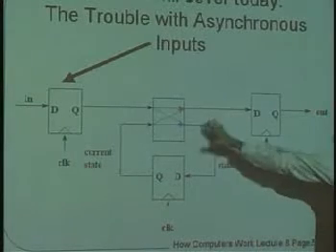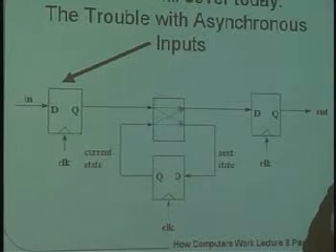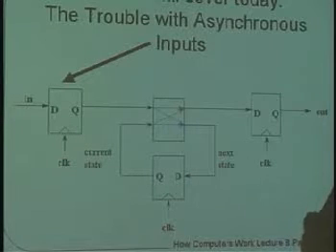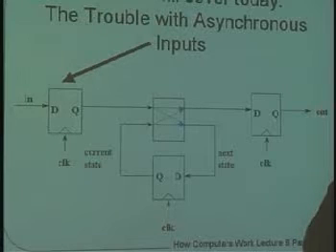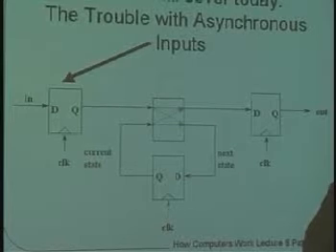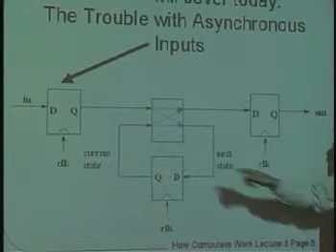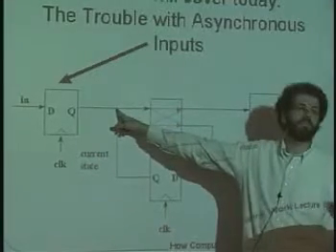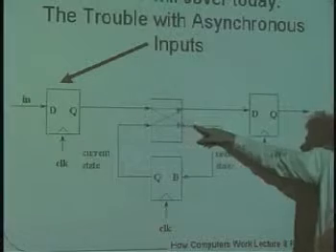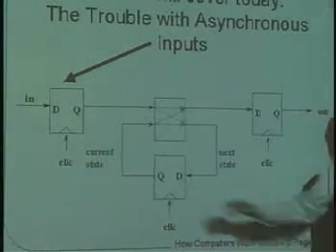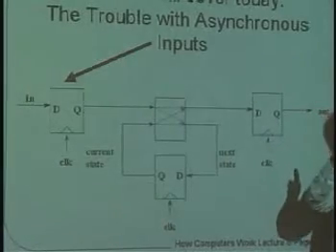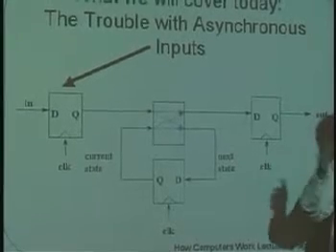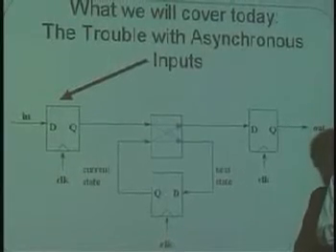And so if our finite state machine, you remember we did the example of the Coke machine the other day, if the nerd who comes up to the Coke machine presses the Coke button, the nerd is not going to sit there with a stethoscope or any other kind of scope and observe what the clock is of the system and push the Coke button just at the right time so he does not violate the setup and hold times of the flip-flop. It's possible that he's going to try to affect an input here and that will propagate through here and come in here just at the wrong time, just when the clock is going off. In other words, inside of the window between the setup and the hold time. And so what are we going to do to fix that?